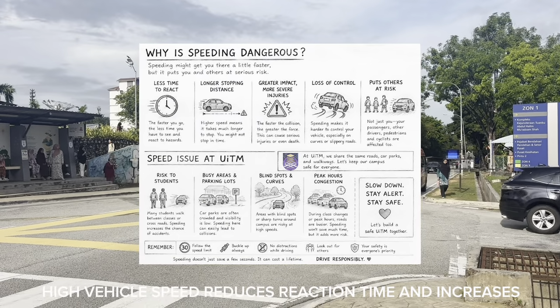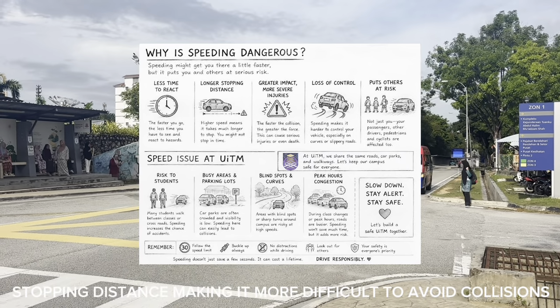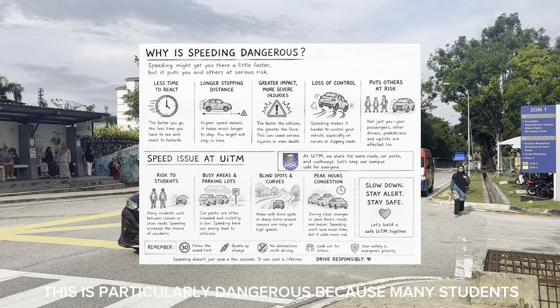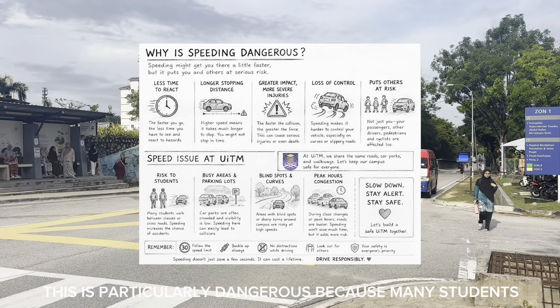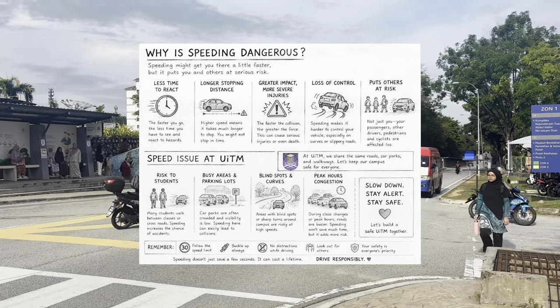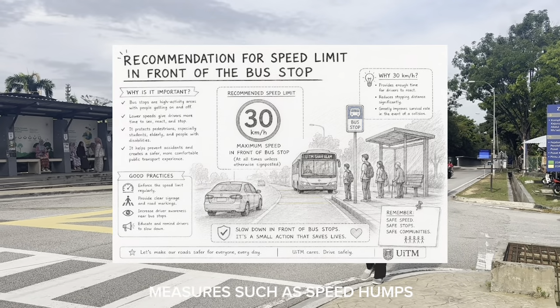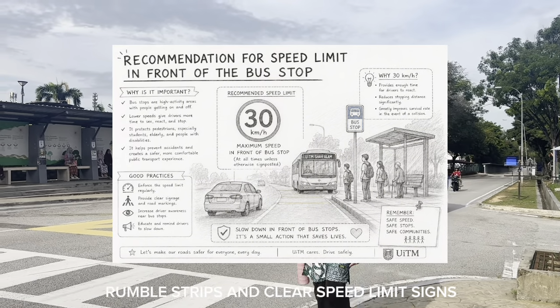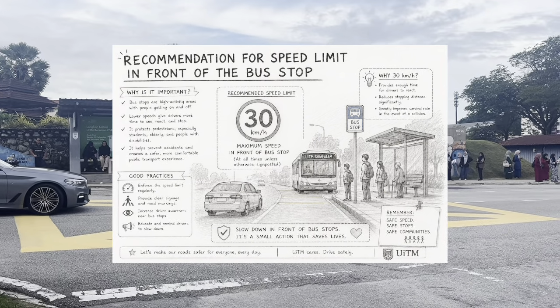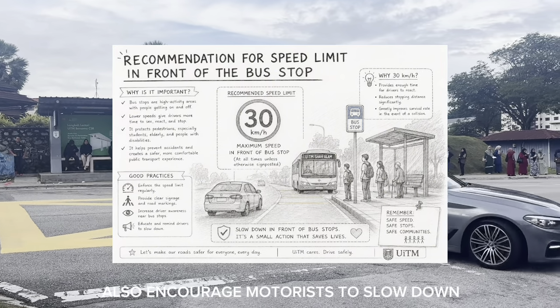High vehicle speed reduces reaction time and increases stopping distance, making it more difficult to avoid collisions. This is particularly dangerous because many students and staff frequently cross the road or enter the exit nearby parking areas. To improve road safety, additional traffic calming measures such as speed humps, rumble strips, and clear speed limit signs should be installed. Regular enforcement and driver awareness campaigns can also encourage motorists to slow down.